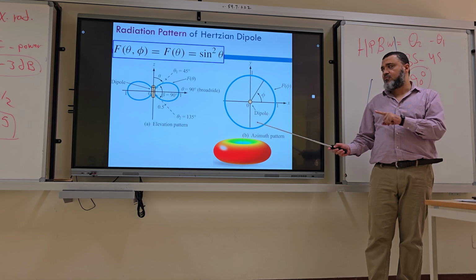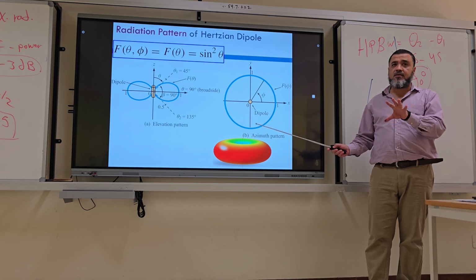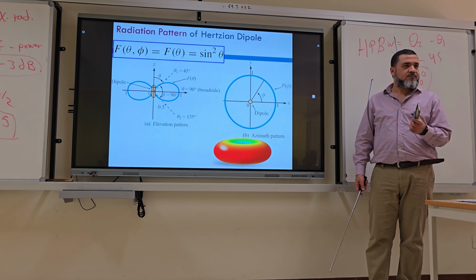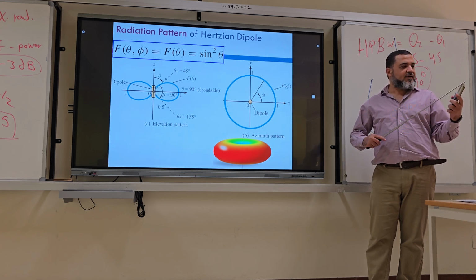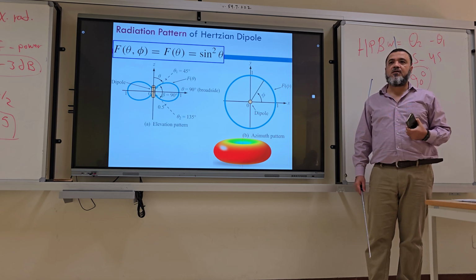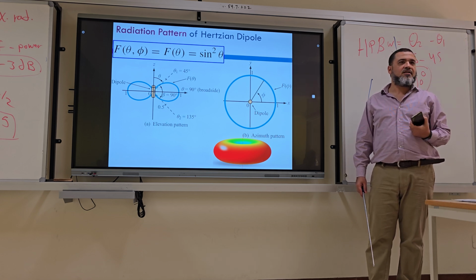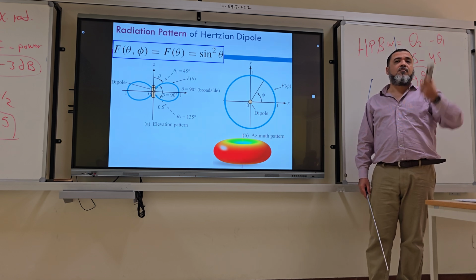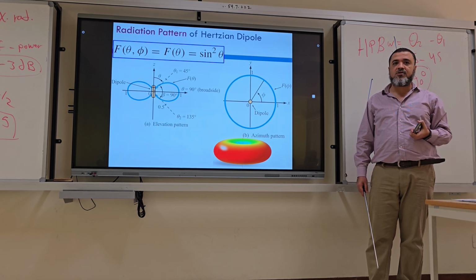No. This is because this radiation pattern has low gain. The gain of the antenna in your phone is 1 to 2 dB, not that high, because you usually have to be closer to some base station to receive a signal. If you go out in the desert, you receive nothing, right? Because you are away from base stations, the stations you see above the high-rise towers.